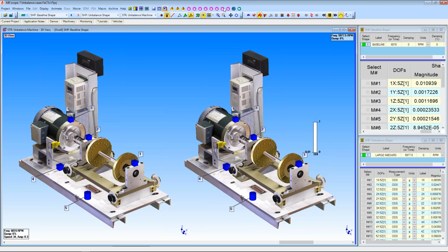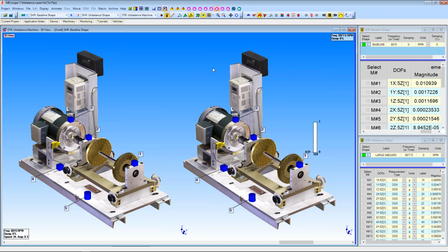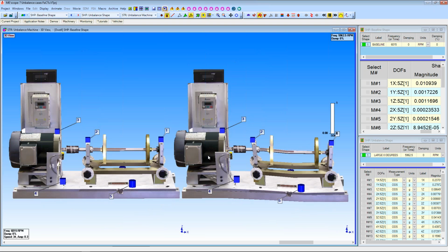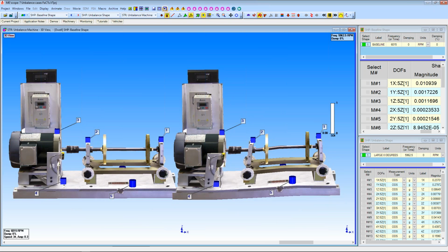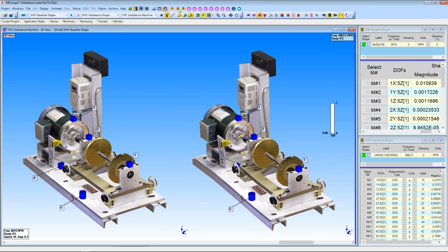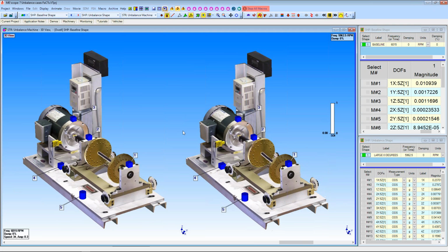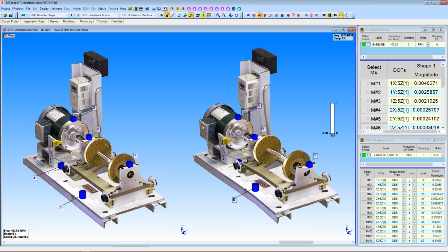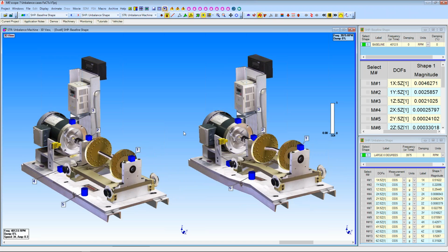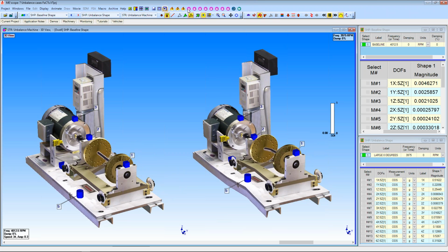Let's go to the worst case again, the 0 degrees of unbalance with the third order. Again, STI is very low. Now the machine is really moving around with the third order, and you can kind of see all that happening here versus the balanced case. Let's go back to the second order. This is the worst unbalance. Again, you can see that base plate is really moving around versus the balanced case. And then if we come back to the balanced case, everything will be the same.